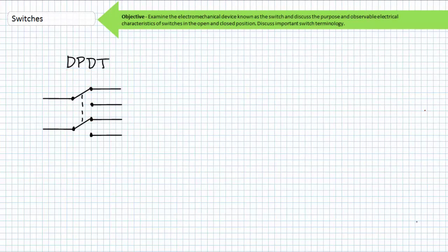Consider a double-pole double-throw switch. This device has two poles that can be placed in one of two positions. This is almost like two ganged single-pole double-throw switches mechanically linked together with a single action. The top single-pole double-throw switch is electrically isolated from the bottom single-pole double-throw switch. However, the B terminal on the left is now the common terminal, servicing both the A and C terminals on the right for the associated switch.